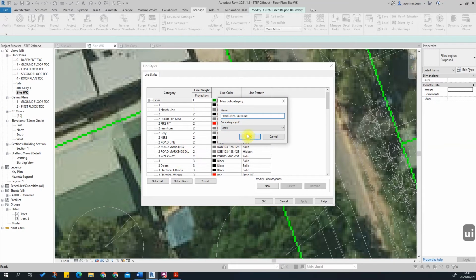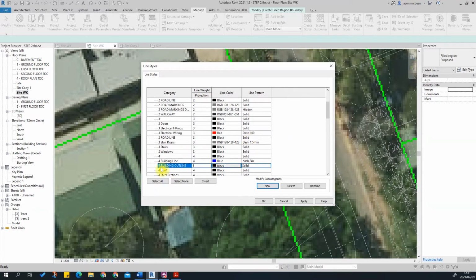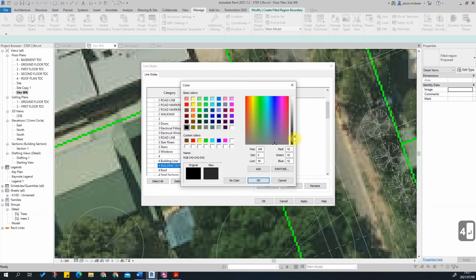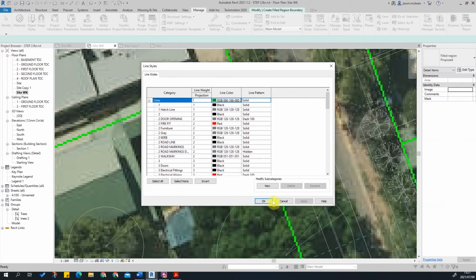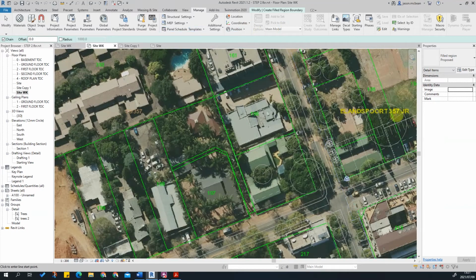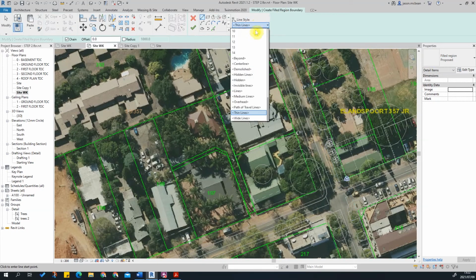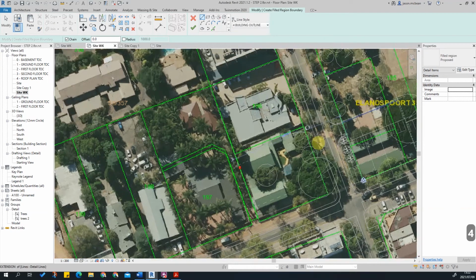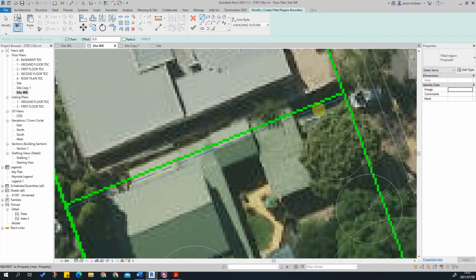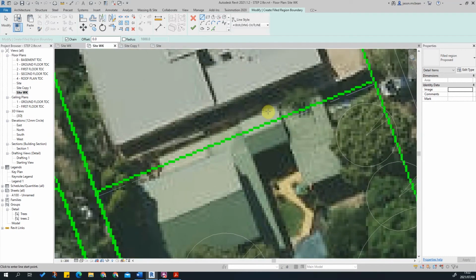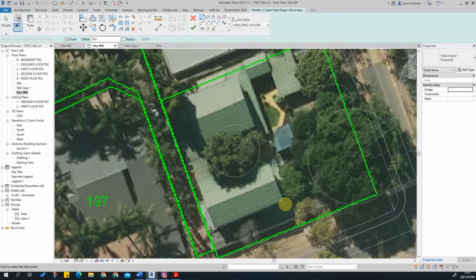Okay, so we just need to add this building outline. Okay, just remember that needs to be 4. And we're going to make this also a slighter gray just because it will define it a bit better. Okay, now that I've created that line work, while I'm in the command, I can simply go and find my 4. Simply hit 4 on your keyboard, jump up here, building outline, and we're simply going to start tracing along the site cadastral information. You can see this building's got a couple steps. So here I'm simply going to start tracing perpendicular, come back to here.